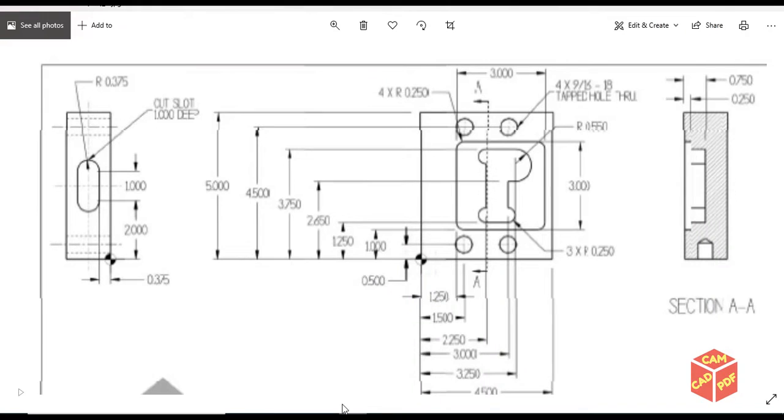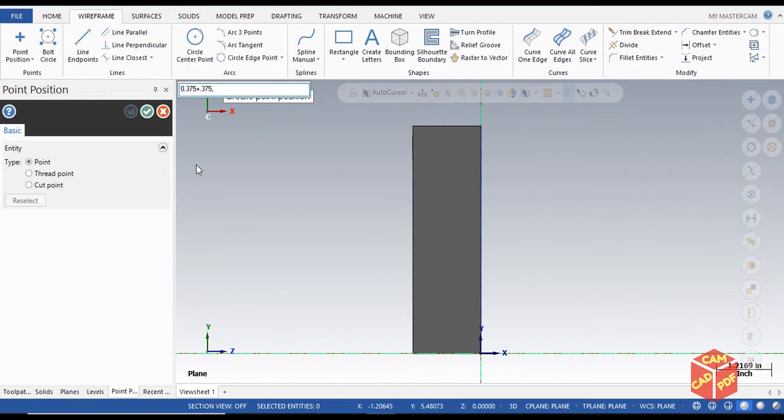Our Y is gonna be 2 inches from our bottom. Over here you can see 0.375 is in the positive direction, so let's see if it works. I guess it should work. We put negative outside and put a bracket, hit enter. Yeah, it works. Because we are not going this way, this way is the positive direction and this way is the negative direction in X coordinates. That's why I put negative outside of the brackets and then put the value.